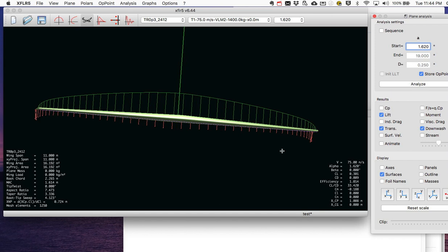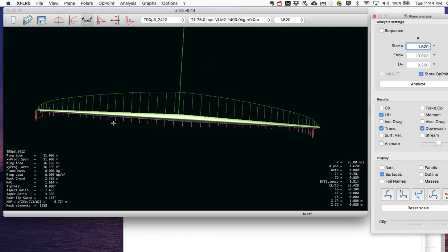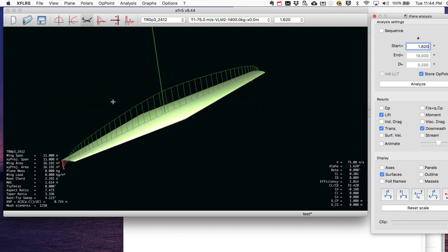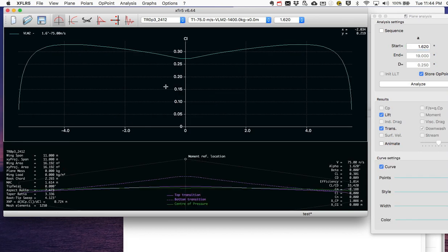This is a little hard to get rid of the very tips, but that's okay. But I'm getting a straighter downwash across most of the span of the wing compared to the rectangular case, but it is certainly not that optimal constant distribution that we spoke about in class. And I can look at span-wise distribution. Here's the lift coefficient, and you can see it's kind of funky that you're getting higher lift in the mid sections of the span.